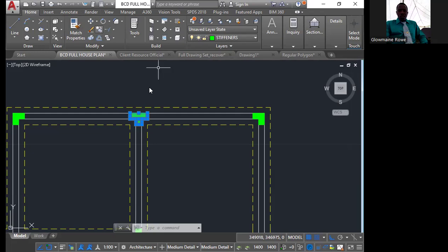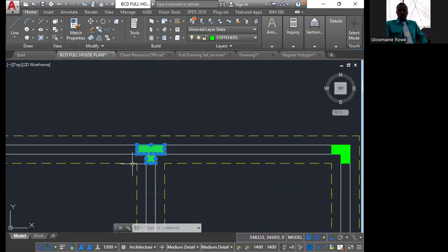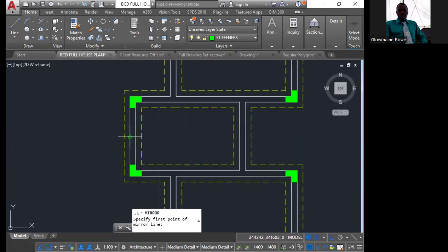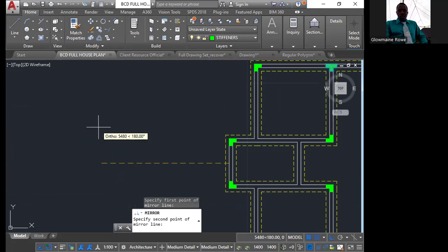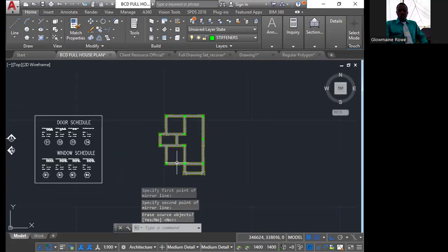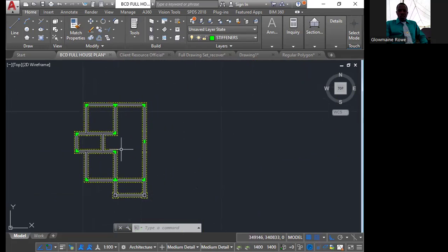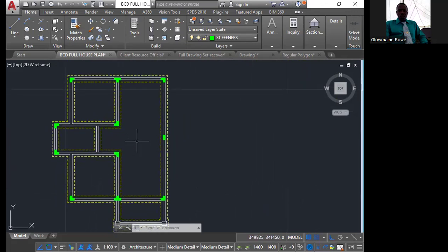All right, so we're copying this. And if we're going to mirror it, instead of copying this, mirror it. I like this stiffener in the center right here in between the bedroom and the kitchen. Use the mirror command. Find any one of the midpoints between the object and its destination. Click. Pull your cursor out to the left. Click again. Press enter. All right, so that is it for your stiffeners.